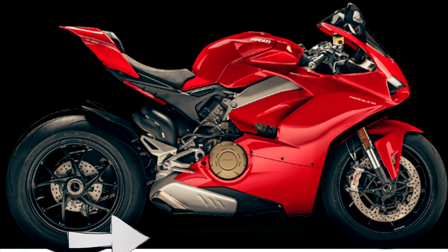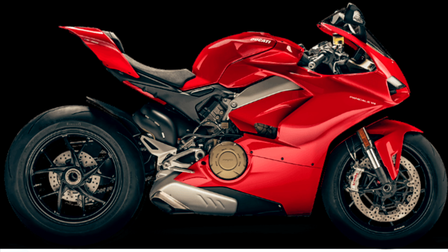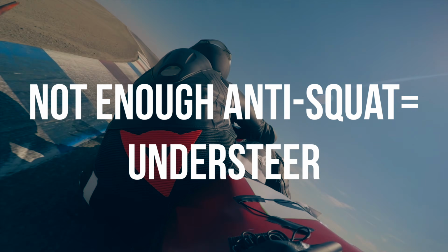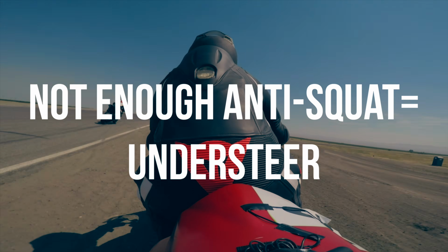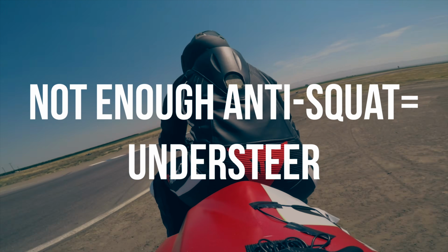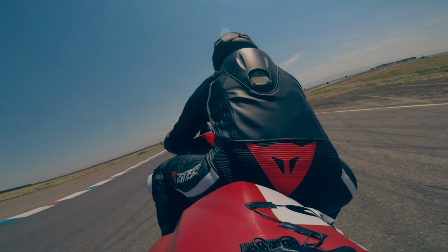We must remember that the rear wheel moves in an arc when the suspension compresses and extends. This alters the swing arm angle and thus the force is generated. If the rear end squats too much, you will lose traction on the front tire because of load transfer, causing the bike to understeer. If you are experiencing this on your motorcycle, you need more anti-squat.